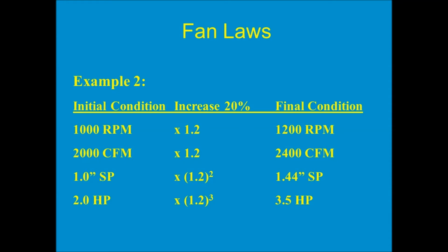Please put a new set of pulleys on order so we can speed up that RPM, and that ought to cost about 50 bucks, right? Well, we have to say, hold on a second, let's run this by the fan laws and see what really happens. So when we input the data of the existing fan, how it's running, and we apply the fan laws for that 20% desired increase in CFM, we discover that the horsepower goes up